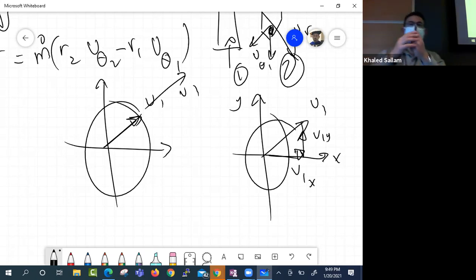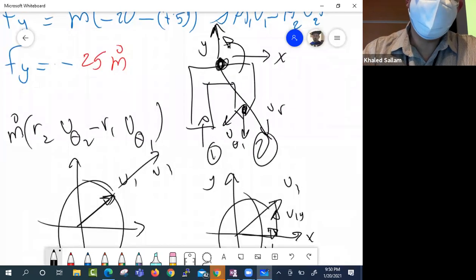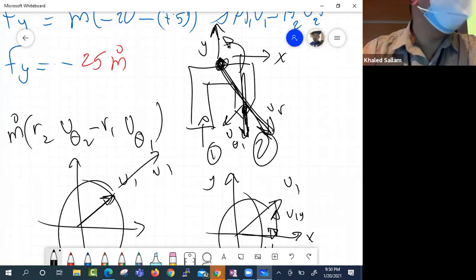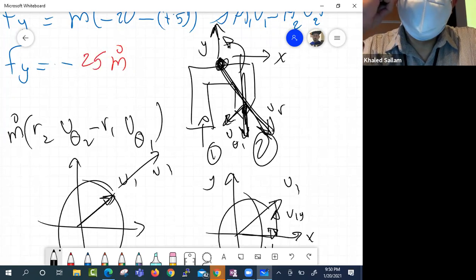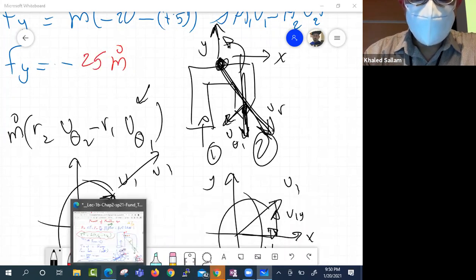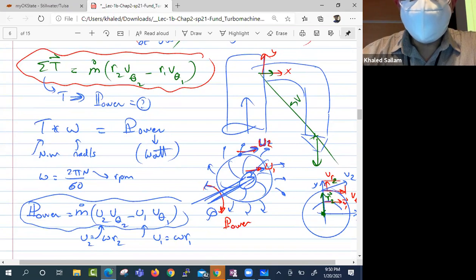Imagine a hose with the water coming out radially everywhere. Will it twist? It will not, because it's all radial. But if it has a tangential component, there will be a torque. So what I'm trying to say is that the radial component of V1 does not twist the thing. It's only the tangential part that wants to spin the elbow. And so this is the tangential component of it. Okay, it will be clear when we start looking at a water pump.